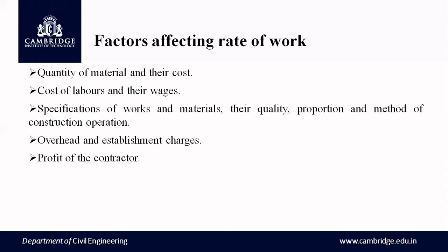And next one is the specifications of work and materials, their quality, proportion, and methods of construction operation. Specifications of work, like different specifications: first class brickwork, second class brickwork, stone masonry, earthwork, and their quality. Say for example, for RCC, PCC for foundation, PCC 1:3:6.